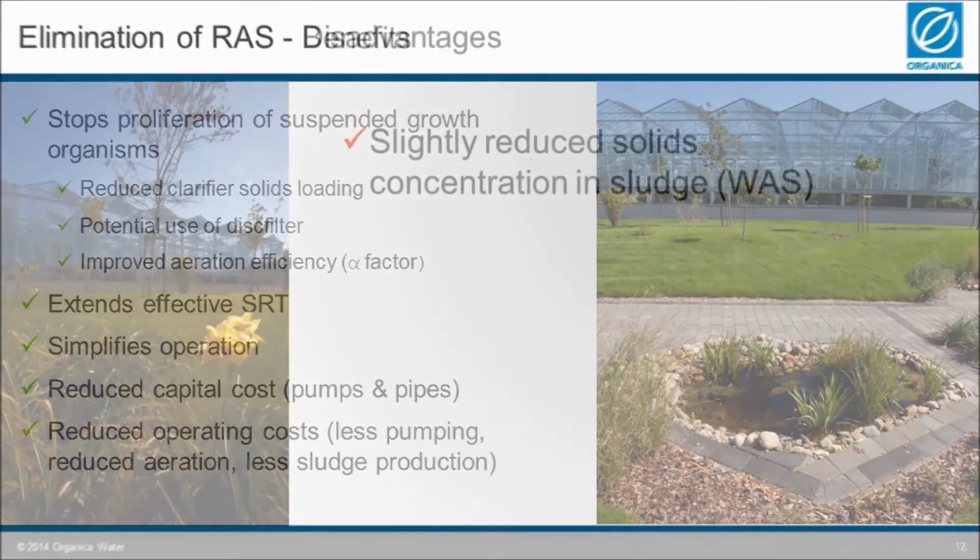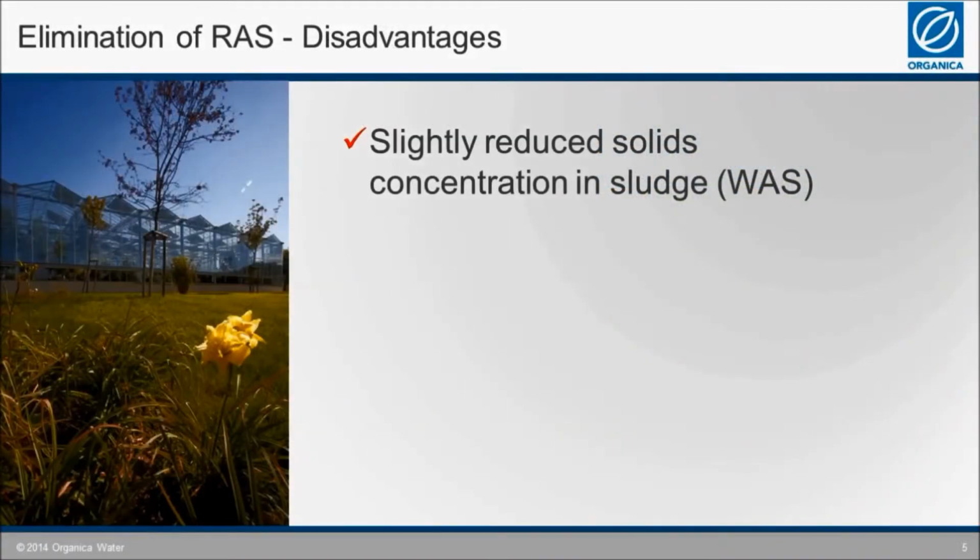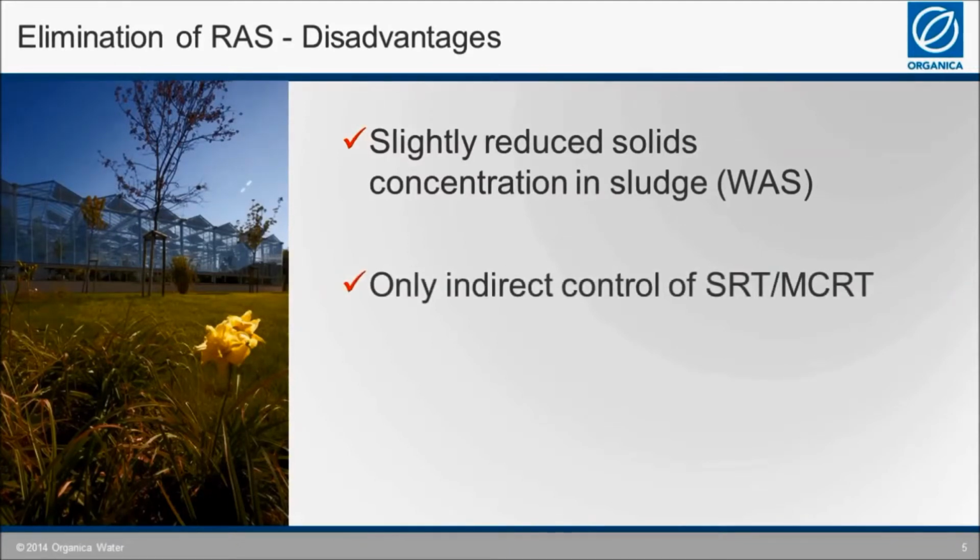On the disadvantages, there's only a couple. None of them are major in significance, but you do see a slightly reduced solids concentration in your waste sludge that is sent off for further processing. You lose the direct control or the ability as an operator to specifically manage your sludge retention time by increasing and decreasing